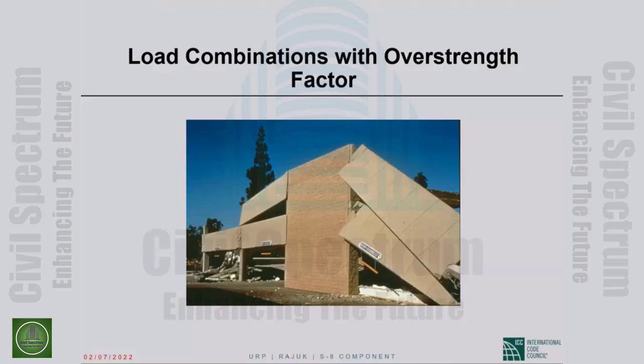And the answer that emerged pretty quickly is that the shear walls didn't have to do anything during the earthquake. And when you don't have to do anything, it's easy to look good. The shear walls didn't have to do anything because the collector elements that were supposed to deliver the shear to the shear walls failed before the delivery took place.